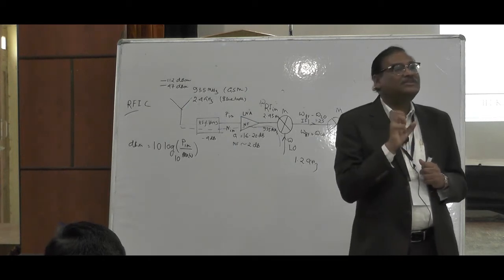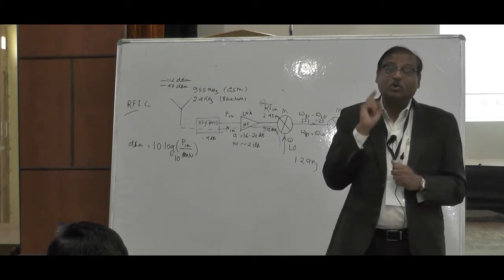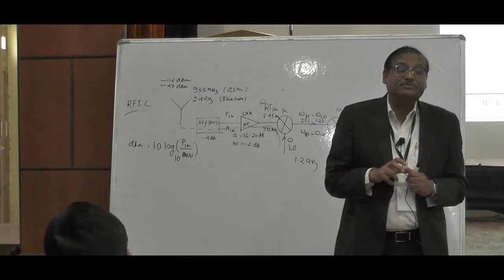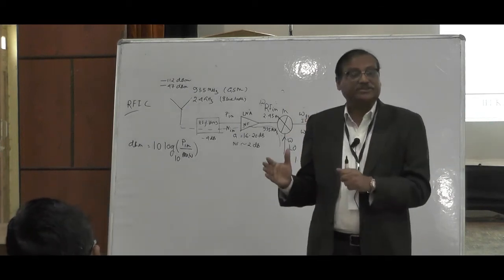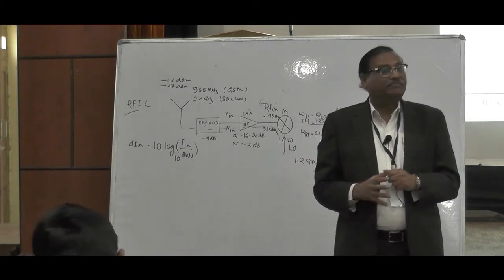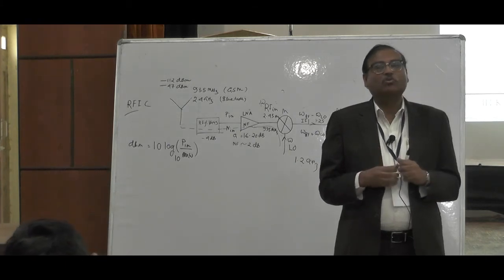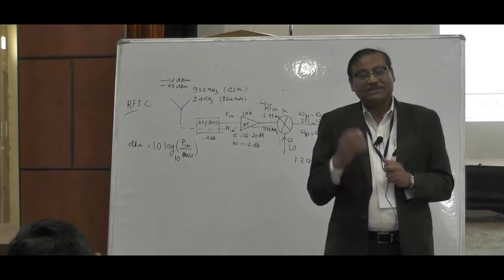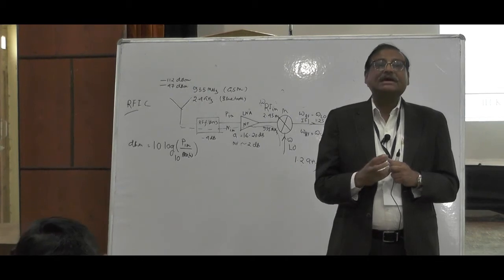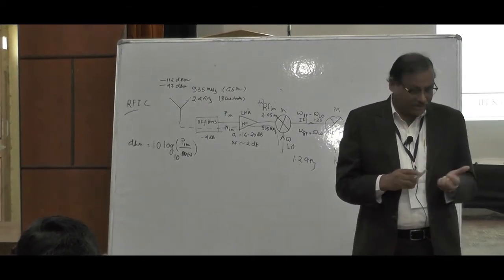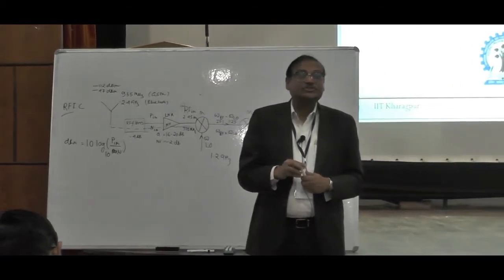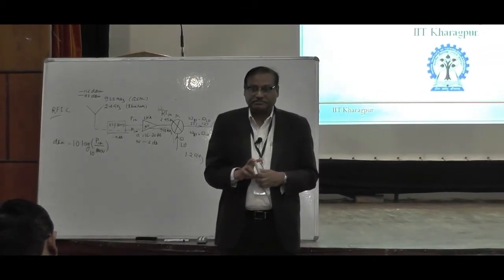That is another challenge: how to make a low-power, efficient front end with the constraint that the passives have a very, very low quality factor. Plus, their modeling is extremely difficult because of the parasitic effects.